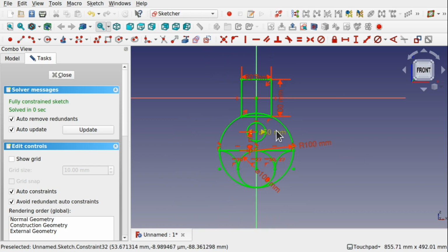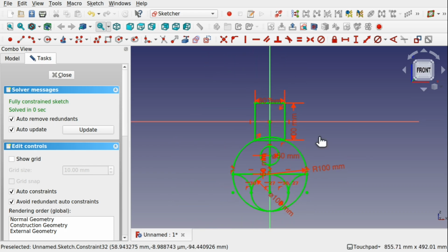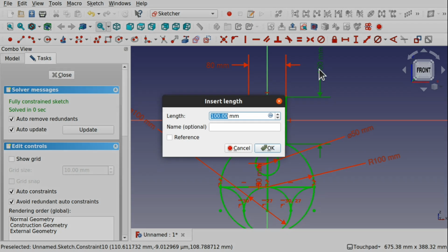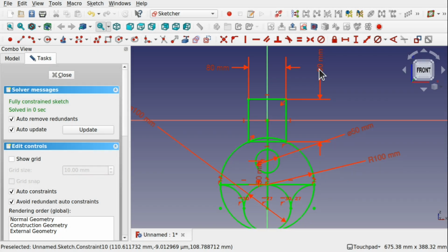So what we've done is basically created a sketch from the profile of our piston. May look very rough, but we can use this as something called a master sketch, and we're going to be using that to understand where we're going to place all our items and constrain them to here. I'm not too happy with the height, so I'm going to do some amendments to make that something like 90 mil.